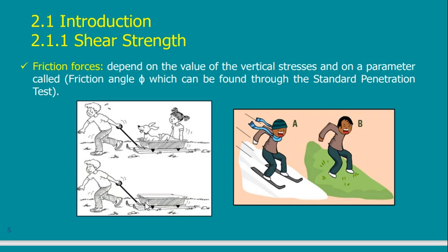You can take the force and use the sine or the cosine of the angle. But if I tell you I have a horizontal force, what is the component of the horizontal force in the perpendicular direction? Zero. Because you are going to use 90 degrees, and that ends up multiplying by 0. But in our case here, this boy is pulling horizontally and the load is applied vertically.